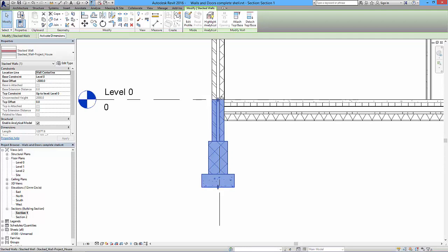What I've also done, once I've put it in, is aligned it. I've lined each face with this. Now I could have worked out what the offset from this wall and this center line was, and then juggled it a little bit, but it's probably easier just to put it in at the right height and then do your adjustments later on. So it was sitting over here somewhere, so I used the align tool and just aligned these faces, so I know that these two faces are sitting perfectly in alignment.